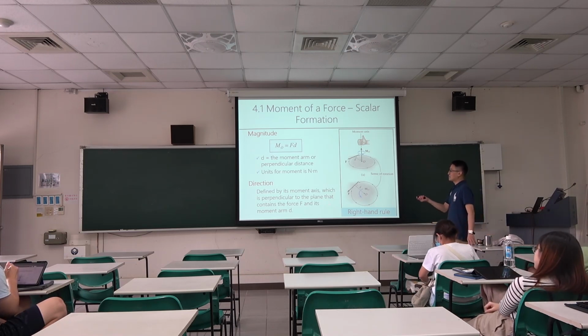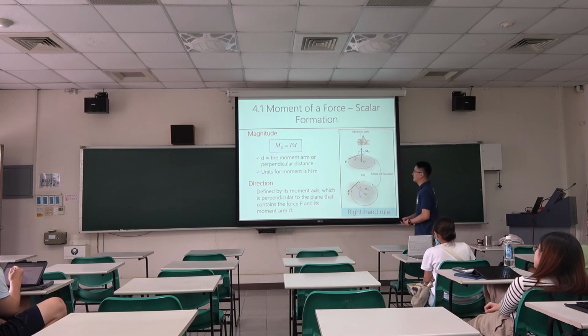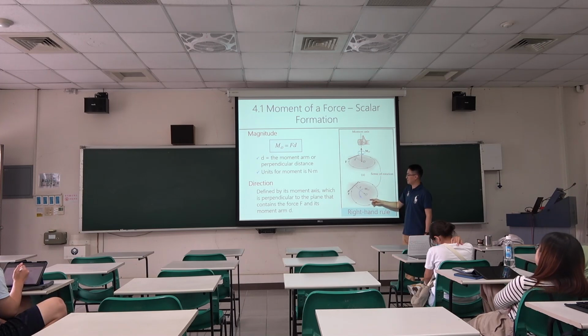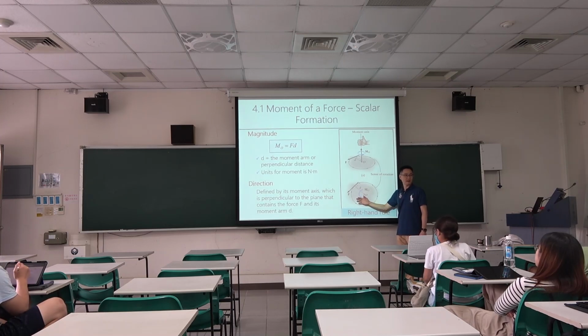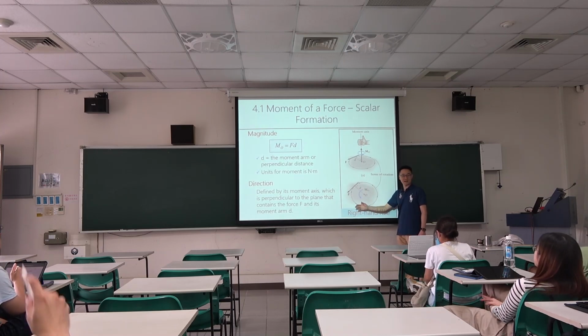Direction is defined by its moment axis, which is perpendicular to the plane that contains the force and lever arm. Using this one as an example, the force and lever arm are both on this plane.